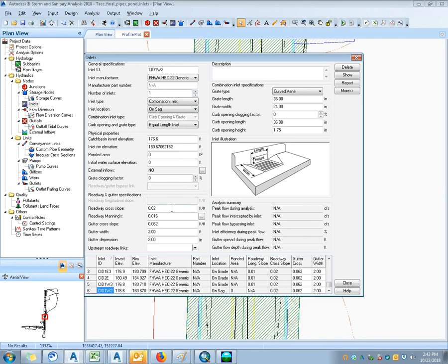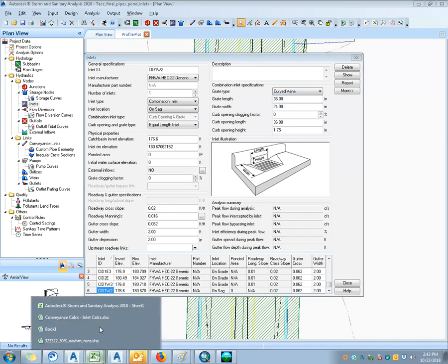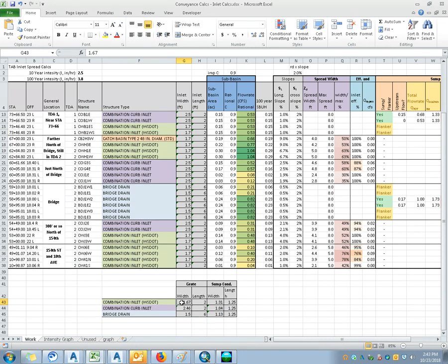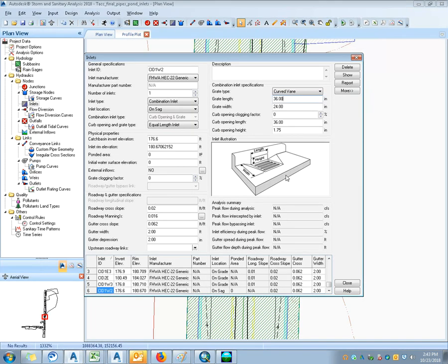And then a few things to set up this value. I think our standard WashDOT inlet is 2 feet by 24 inches by 20 inches. So we make this a little bit smaller. You can adjust your clogging factor. All this stuff is in the WashDOT manual. I have to kind of look it up to see what it needs to be.